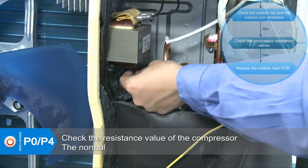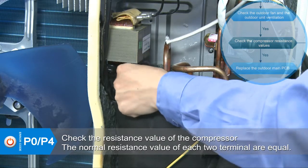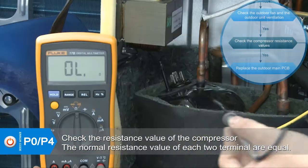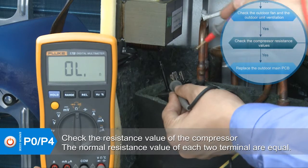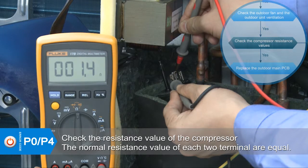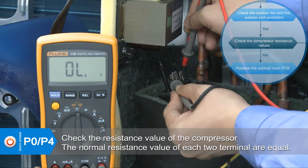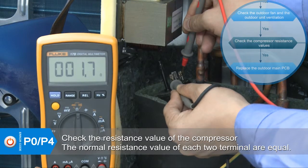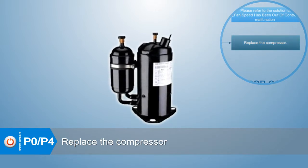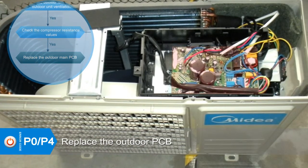Check the resistance value of the compressor terminals, and check if the compressor is working well. The normal resistance value of each two terminals is equal. If the resistances are not equal, replace the compressor. If the error still exists, replace the outdoor main PCB.